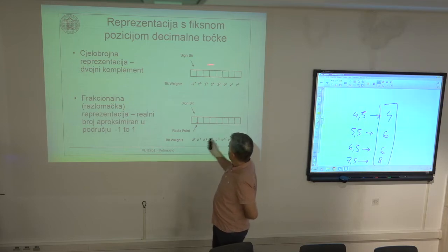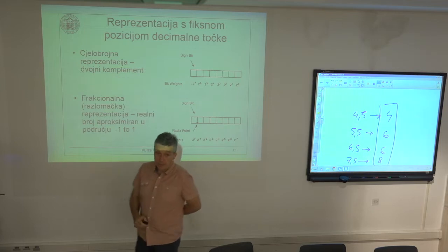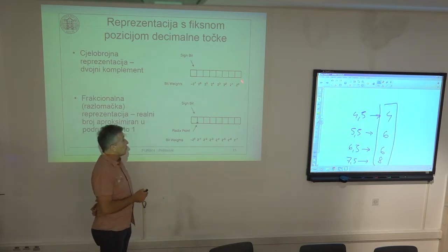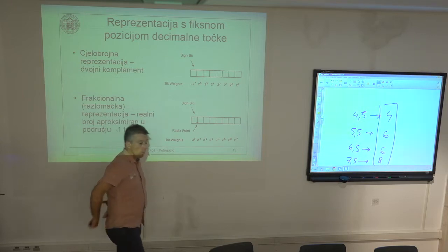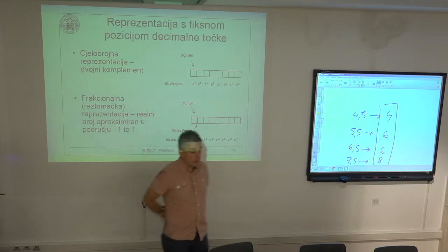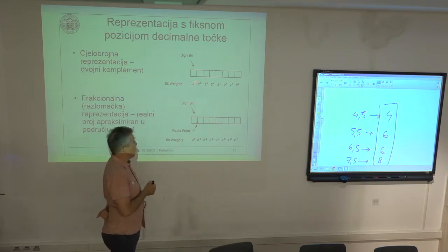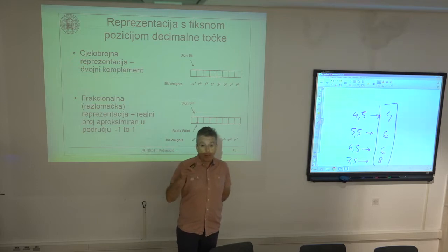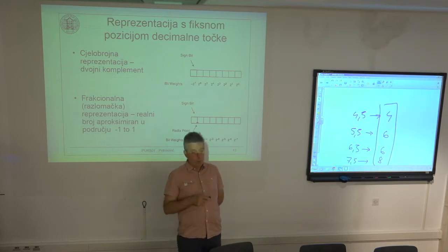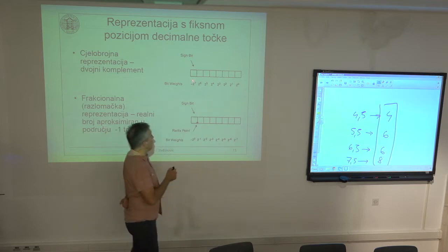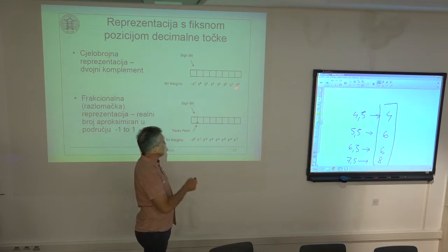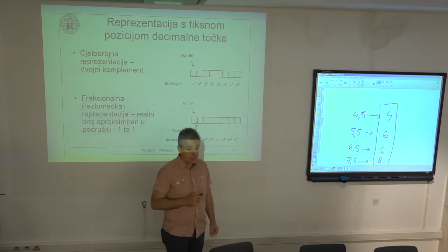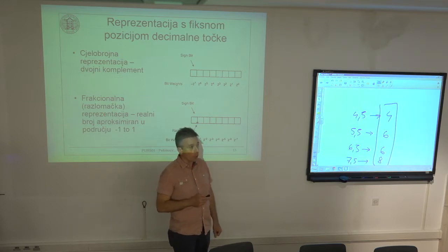If it is 2's complement, then the weights of the individual bits are 2 to the power of 0, 2 to the power of 1, up to 2 to the power of 6. And the most significant bit is actually a sign bit. It has the weight of -2 to the power of 7. So if this bit is set, then you have to add -128. So 2 to the power of 7 is 128 with a minus sign. So actually the value of 1 with all zeros is equal to -128 in the case of 8-bit 2's complement representation.